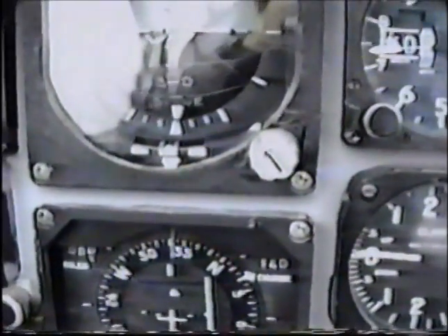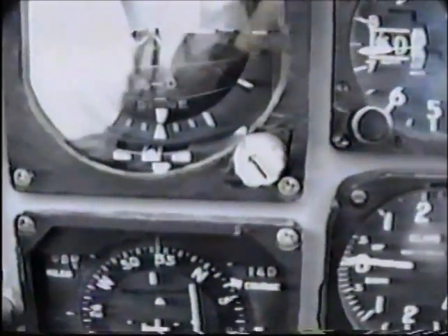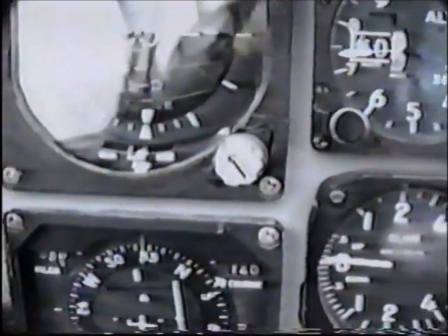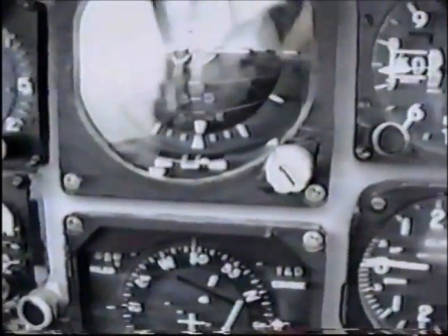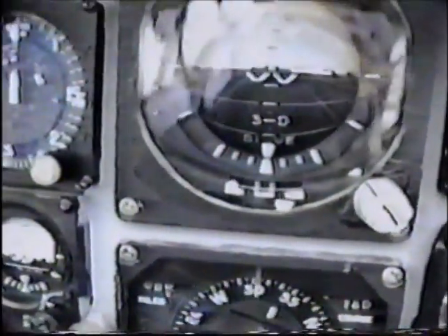As you maneuver your aircraft, check the turn and slip indicator and the HSI compass card for proper turn indications in both directions. Don't forget to cross-check with the mag compass. The before taxiing and taxiing checklists are now complete. But before you run off, let me offer you a few tips that you will find not only useful, but often required.